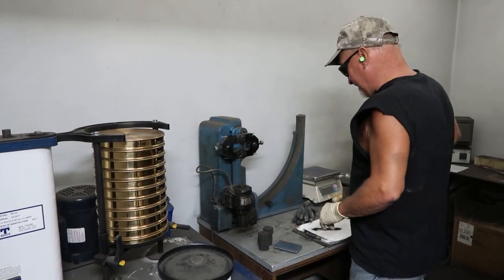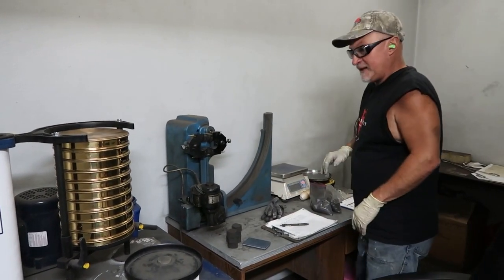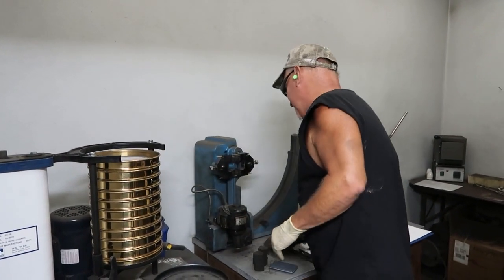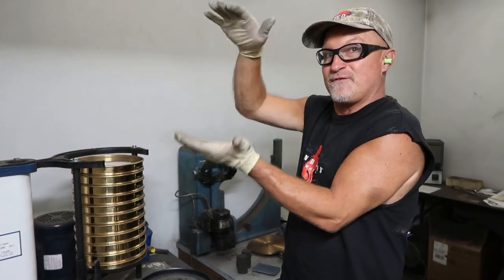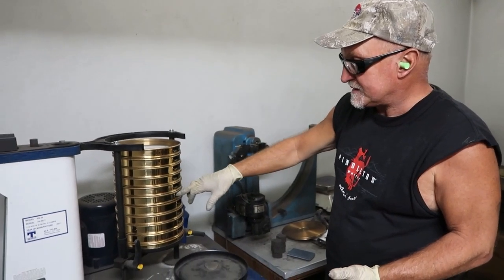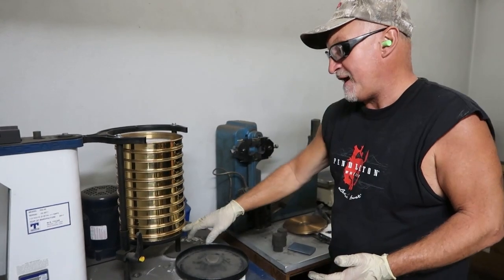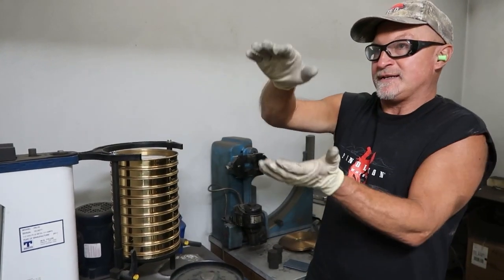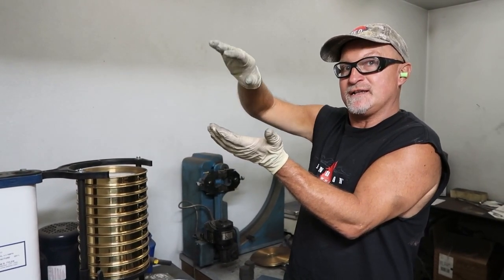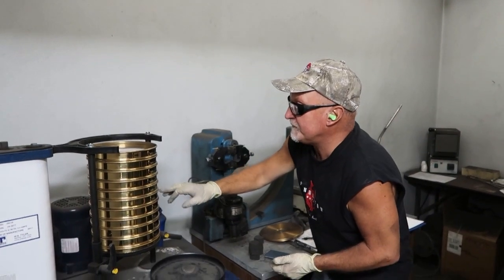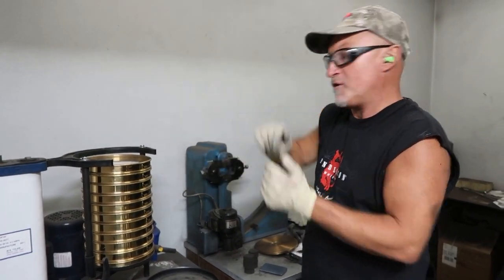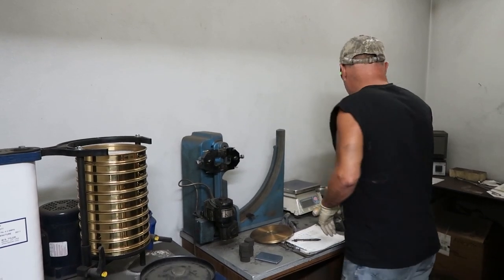We chart, so we have a running chart, and then we do sand sieve analysis to make sure our sand flows equally through all the sieves. We have 1, 2, 3, 4, 5, 6, 7, 8, 9, 10, and then we have our bottom pan. This way I can tell if the sand starts out low, and you make a curve. The 50 and 70 pans are the ones where you want to see your curve go up. And then I document all that.